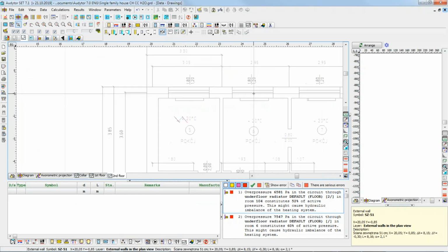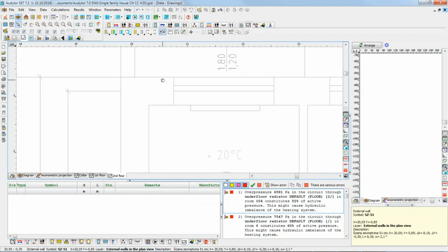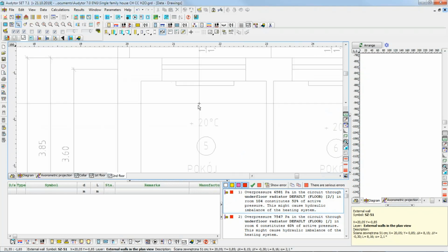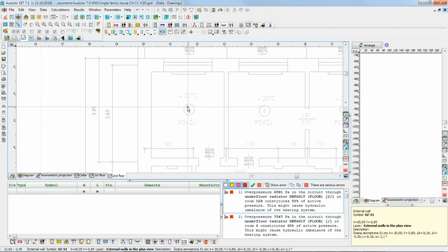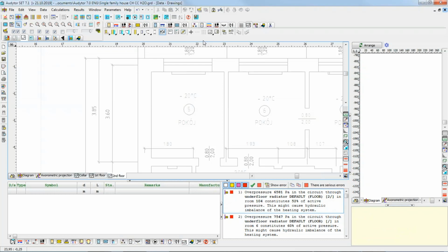The other thing is that you can see that maybe I don't need to draw the walls to have these logical walls. Maybe it's enough what I can see from the AutoCAD file. Yes, it's also possible. Probably it's the fastest way. There is just one thing that is obligatory. This is to create the room zones, because the program needs this information. Each element must belong to one of the rooms. So the minimum program is just to create room zones.